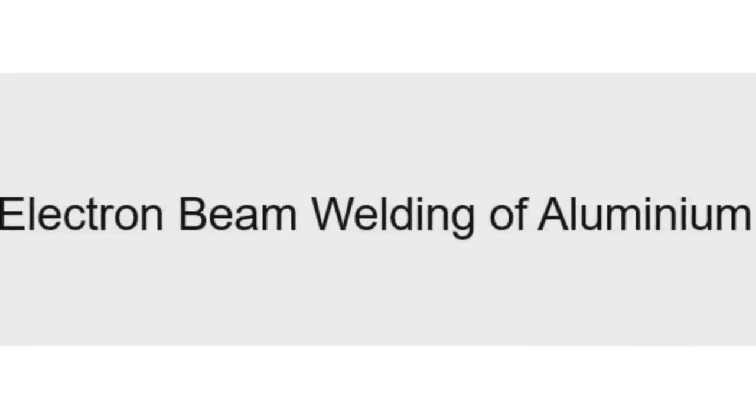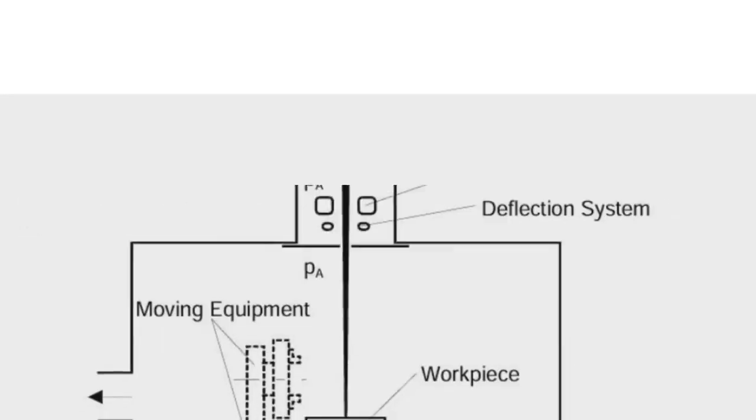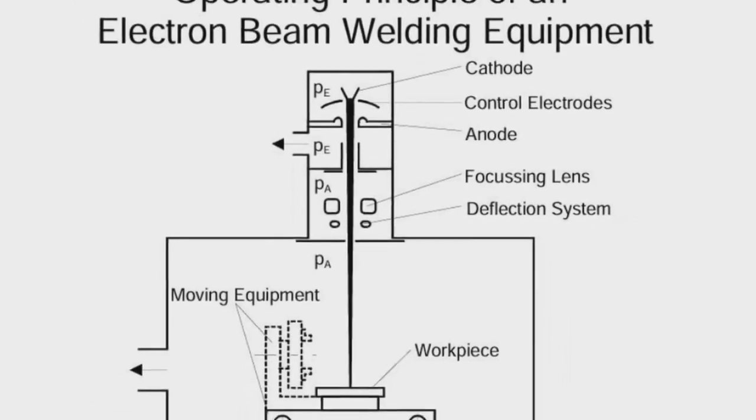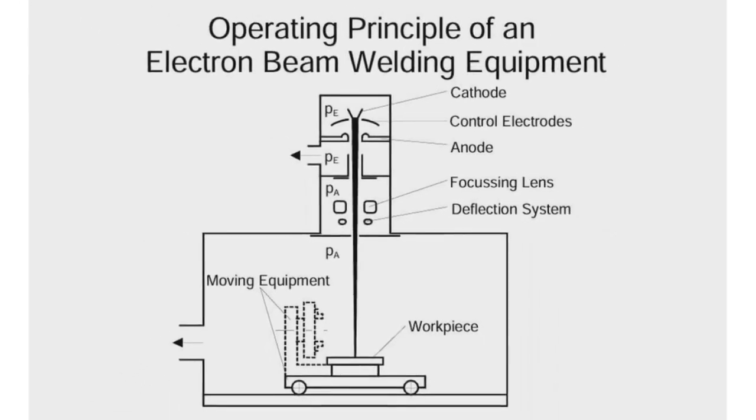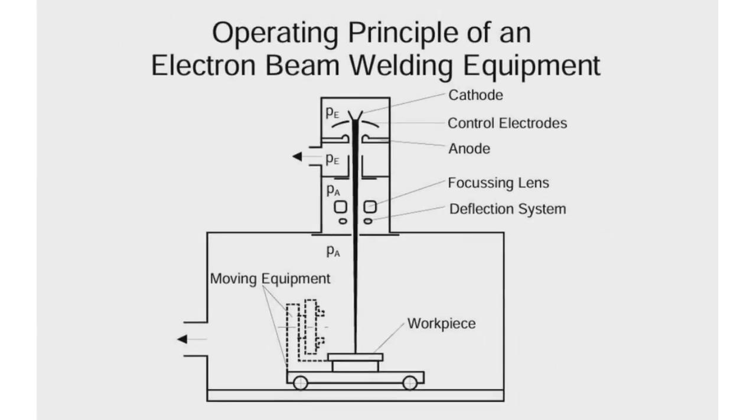Electron beam welding of aluminium. The electron beam welding is associated with energy densities of more than 1000 W/cm². A vaporization of the metal occurs above 100 kW/cm². The electrons emitted from an incandescent electrode and accelerated in an electron gun are focused to bombard the work placed